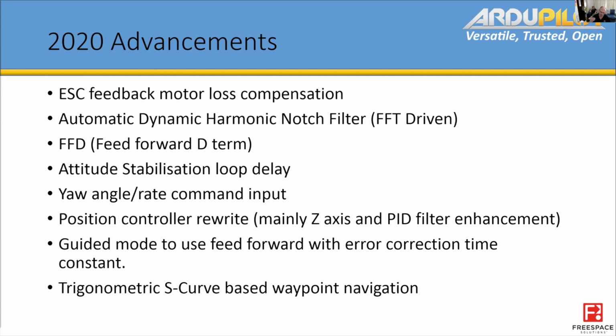Because if we know, not just think or guess, but know what an ESC does, it provides us additional options in how we handle that, and we may even be able to do much more significant change in our motor mixing to get a more optimal performance, or perfect handling of motor loss.